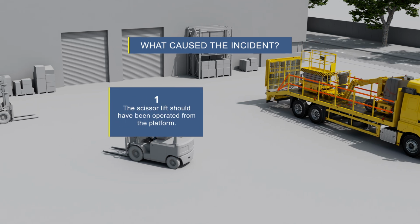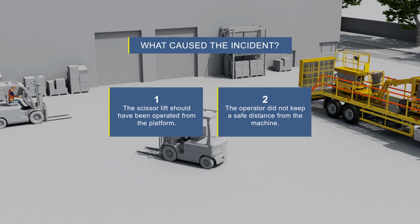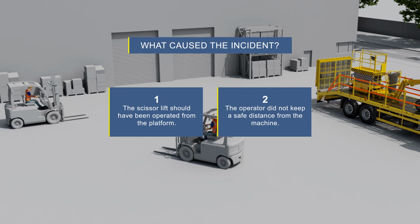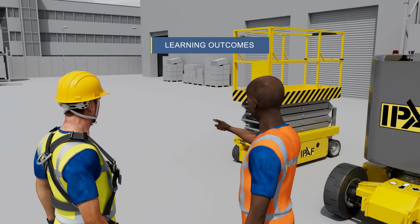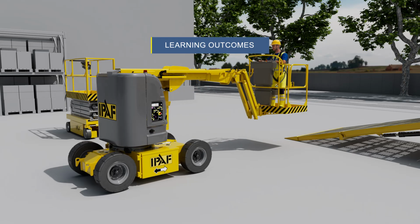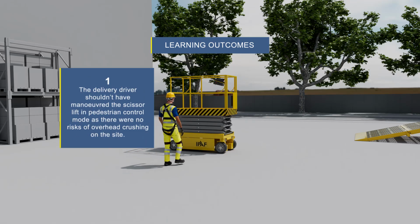In this case, ground conditions were good and there were no overhead obstructions. The scissor lift should have been operated from the platform. If a scissor lift is ever operated from outside the platform, the operator must keep a safe distance from the machine.